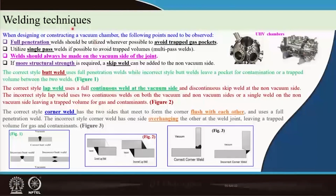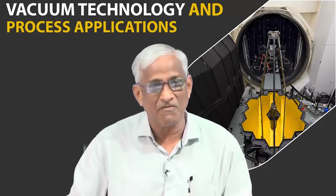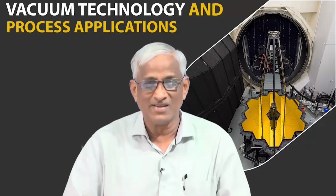So, when you concentrate on welding techniques of such chambers, what do we need to keep in the picture? Full penetration of the welds is required. In fact, recently very costly chambers are manufactured from an ingot itself by scooping out the material, totally avoiding welding, everything inside.